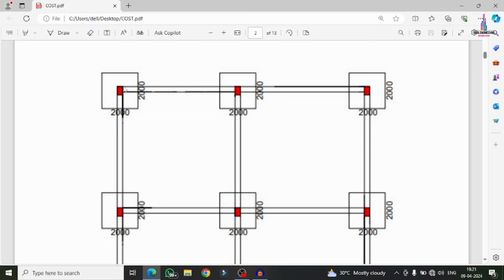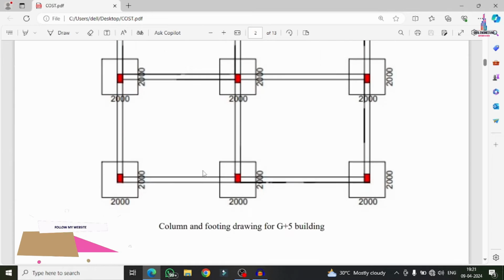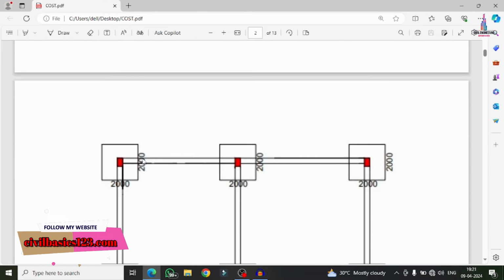Now we can see this is the center line distance of approximately 1 meter, and this is the center line distance of 1 meter. This horizontal length is approximately 4.5 meters. From the 4.5 meters, if I deduct the value of 1 meter, it comes to 2.5 meters. But we have to add the extra thickness of the wall for this section. Why? Because we consider only the center line distance from here, but we have to do the excavation process from this level and from this wall level. But we have to deduct this center line wall distance here, which is nothing but the beam distance here, 0.3.